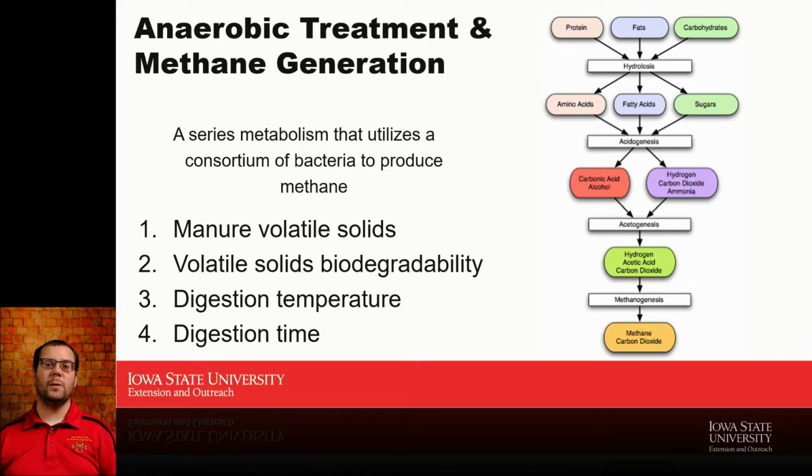One thing that's unique to anaerobic digestion compared to maybe other fermentation processes that you might be familiar with, such as ethanol production for either beer brewing, or for generation of fuels, is that we use a consortium of microbiology, right? So it's all of these different types of bacteria that really make that process happen. When we're making ethanol, we really want to start with clean stuff, clean material, clean tanks, and seed it with very specific bacteria. So this is what I would call a dirty process, right? It doesn't have to be clean. We still end up with the right microbiology present to make that methane, which is our goal.